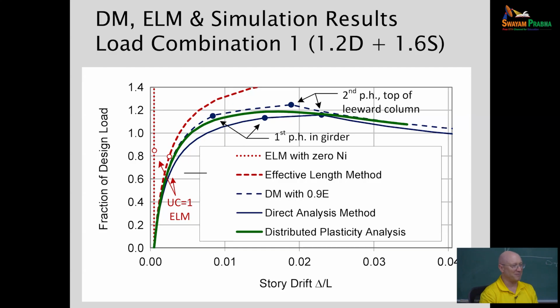And it ends up failing with a lot of bending, right? So it's both a blessing and a curse. If you say, hey, I want to design based on what's really happening, great, good. You've got a better feel for what's really happening. What's really happening can be a bit more complicated than what you're seeing when you run the analysis solution and do the effective length method.